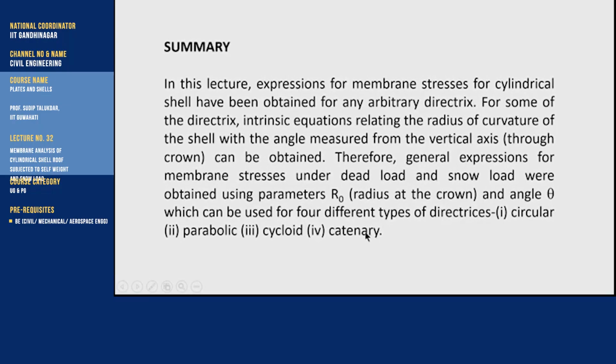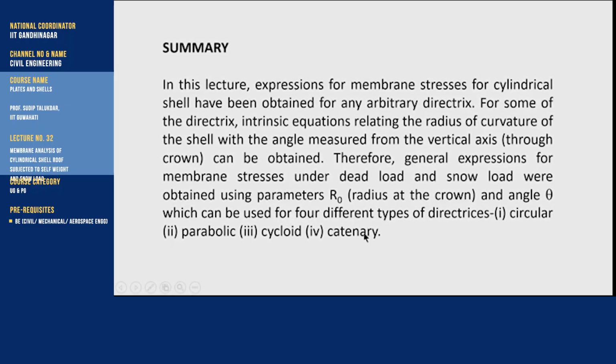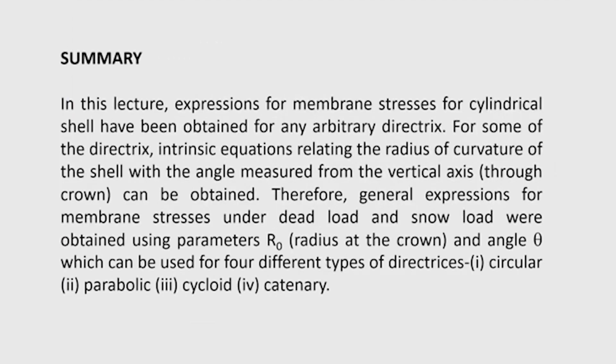So, let me summarize what we have done today. In this lecture, expressions for membrane stresses for a cylindrical shell have been obtained for any arbitrary directrix. For some of the directrices, intrinsic equations relating the radius of curvature of the shell with the angle measured from the vertical axis can be obtained, that is, r and theta are related.